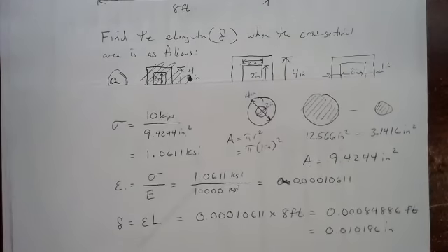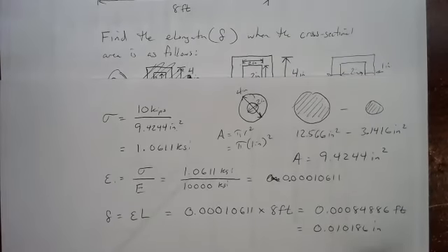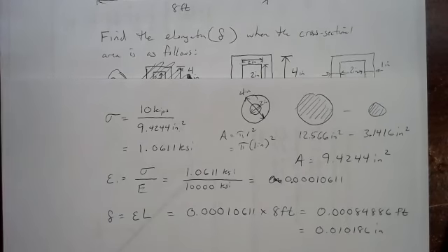So when the stress is going up a little bit, the elongation goes up a little bit too. So would it be safe to round it to 0.0102 inches? Yeah, for 3 sig figs. I don't think anyone's going to break out a laser mic or something that's going to get us down to a millionth of an inch. I rounded in a little bit deeper than you did throughout, but I still came up with the same. Yeah.